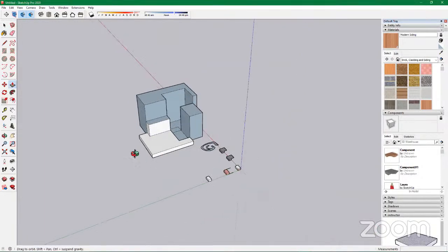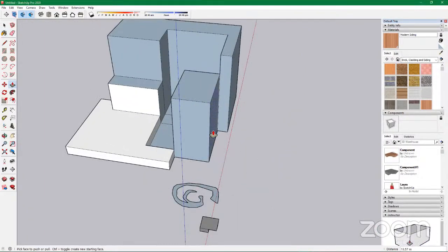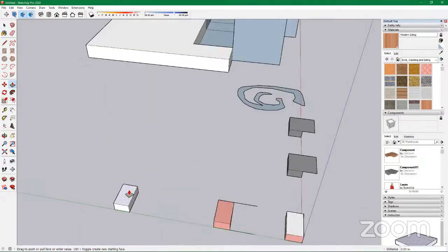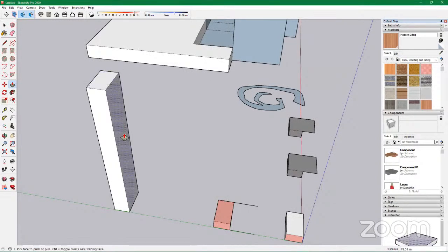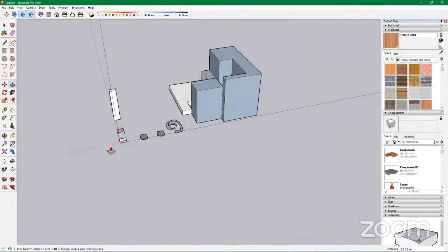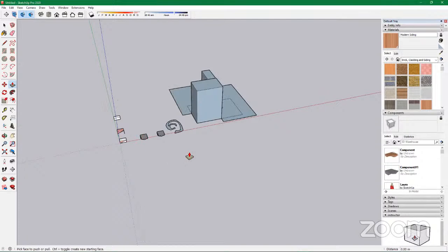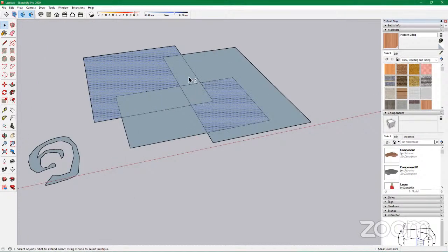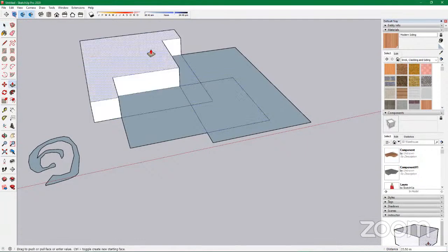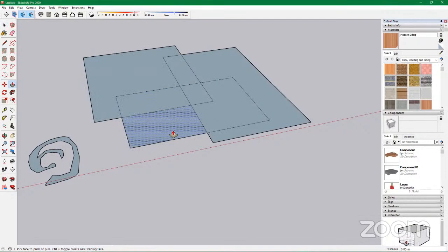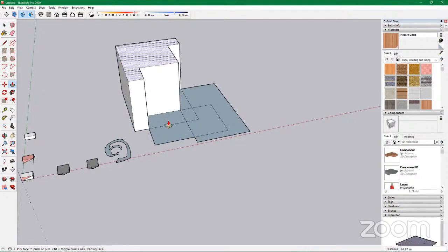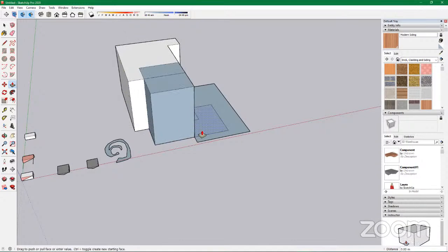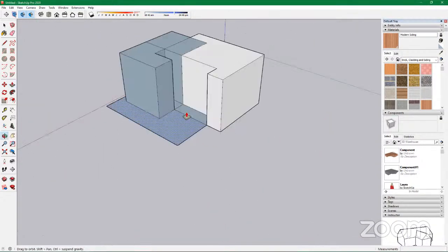If you want to extrude the whole shape, there's no need dividing it. Just go all like so. Or you select all the faces. Let's see if that will work. Let me push both of these first of all. Let's do one at a time. If you want to extrude the whole face, there's no need dividing it. Or you can create one like this and then double click on the rest to meet up with that height. Like so.